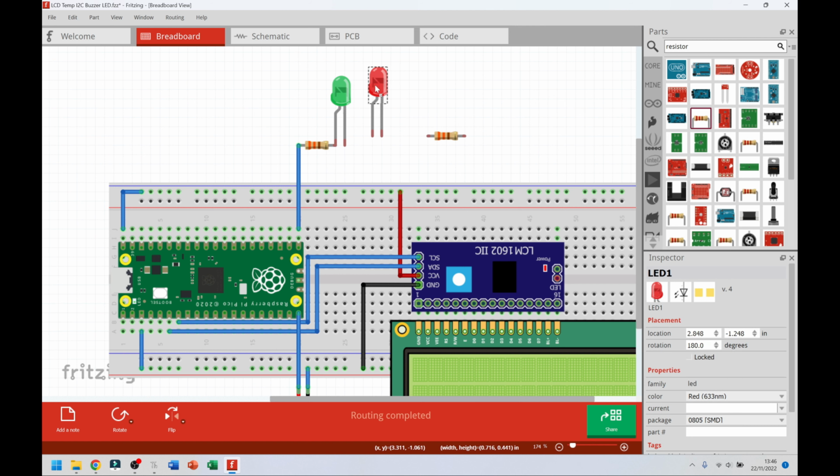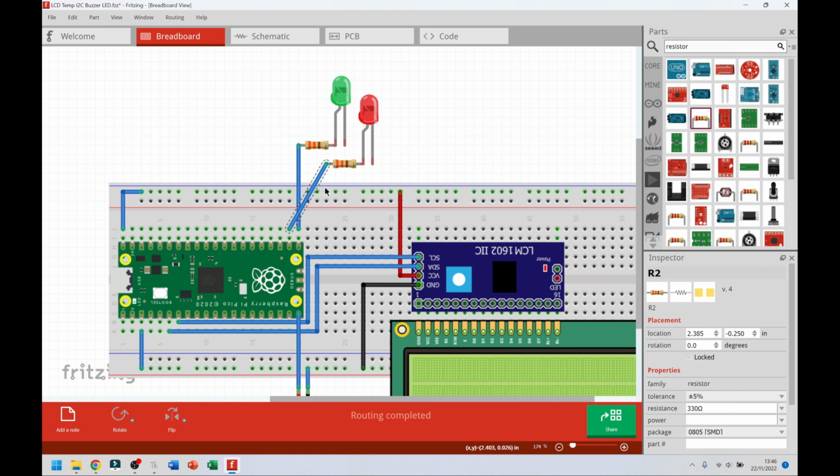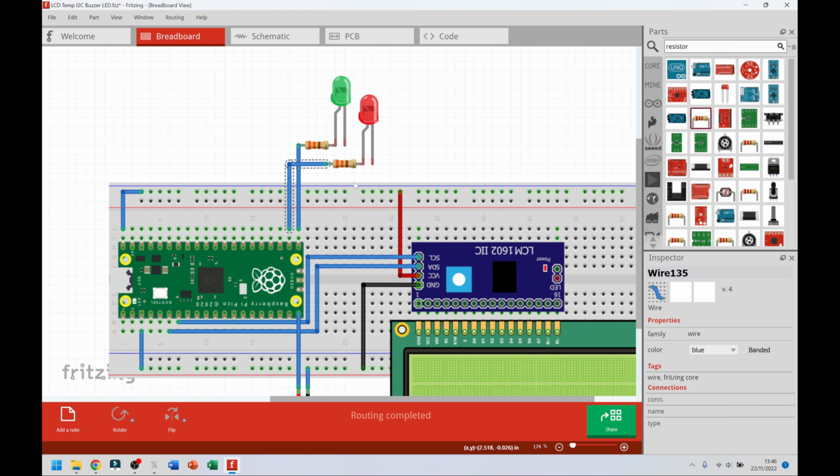Connect that directly to my resistor. Then do the same thing for this one. Now, I'm going to probably put my one a bit higher or a bit lower just so it doesn't interfere with the circuit diagram itself. So I'm going to go here. I'm going to put that one there. I'm going to go from pin 21 over to this one here. I'm going to draw my line like so. And as you can see, it crosses over. But let me change the color of this one so it's very obvious. Maybe to yellow.